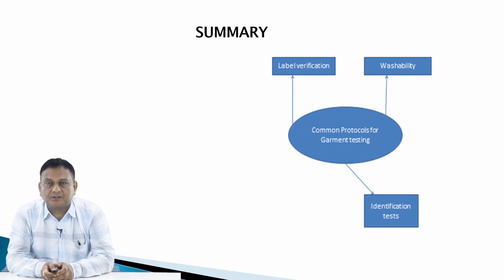And this testing will vary depending upon which kind of product we are taking, whether it is a woven product or a knitted product. So depending upon the requirement, the testing is to be carried out. For example, in woven goods, the tensile strength test is carried out, but for knitted goods, the bursting strength test is done. So there are differences in protocols for knitted garments, and also buyer wise, if it is a US buyer or a European buyer, the test instrument will vary.